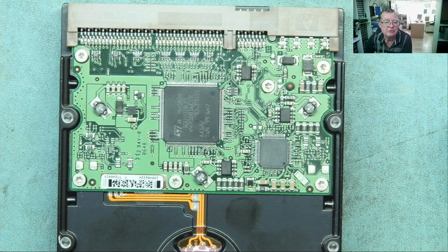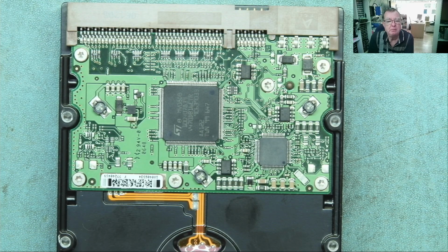With the thermistor, especially if they have blown up, it's caused by something else most likely, causing the device to draw far too much current. For example, short circuit in the outputs. Okay, so that is MOVs, TVS and thermistors. And so to number 12,